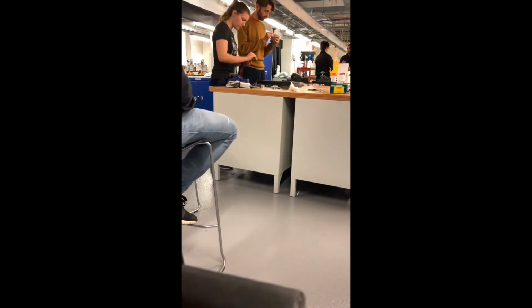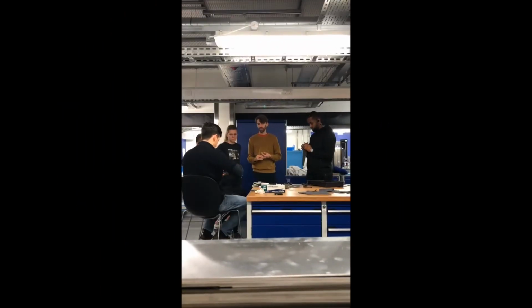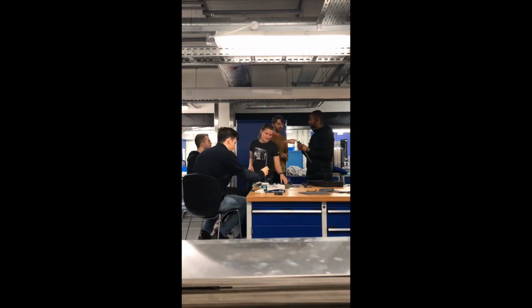We predicted around 3 to 5 grams of excess according to the density of ABS and the volume of the turbine. We could easily sand off this excess and meet the weight restrictions, however, the final weight turned out to be 225 grams. This amount of residue could not be polished off without changing the structural stiffness or aerodynamic performance, hence we decided to stay with this weight. During the polishing stage we slightly damaged the serrations of the trailing edge, but this had little impact on our power outputs.